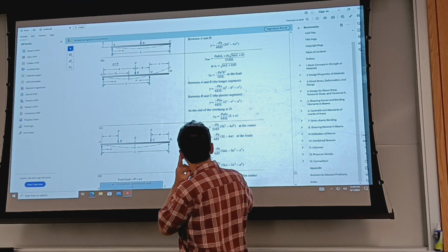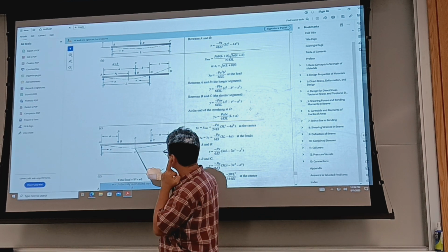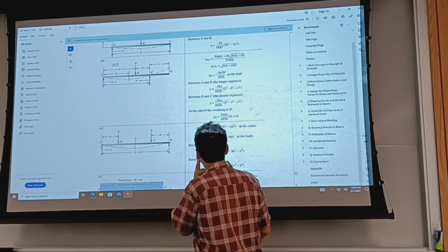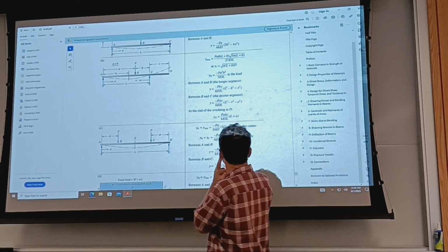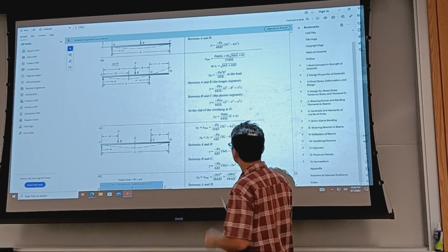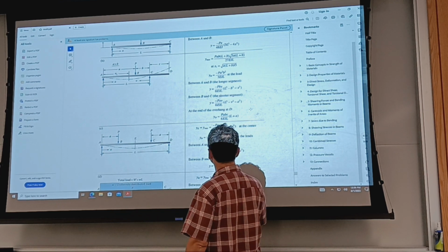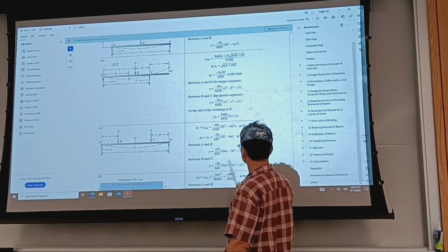And it tells us where the maximum deflection happens. It's at the middle because of the symmetry of loading. What the deflection of the loads is, y of B and C, right there. And then the equation of the beam between A and B would be this equation. Between B and C would be this equation, uses X.